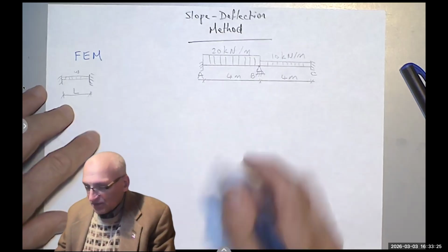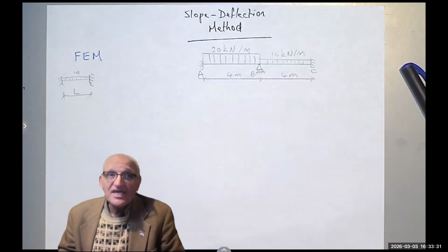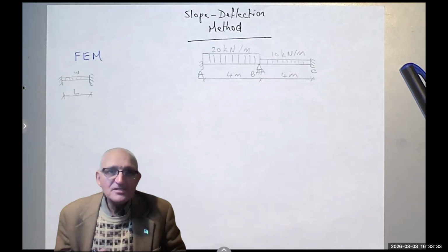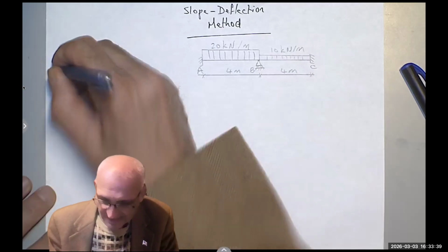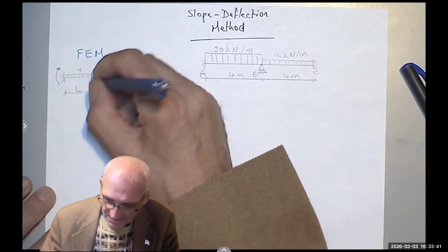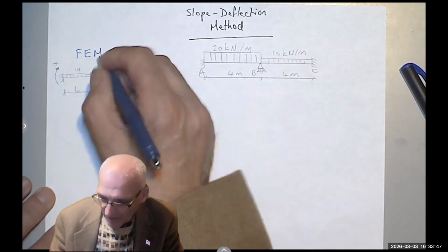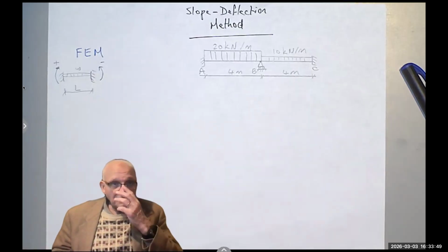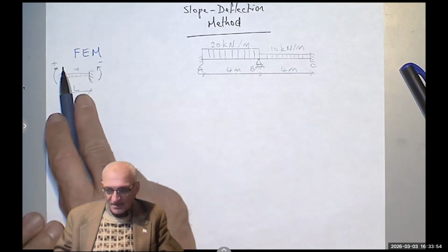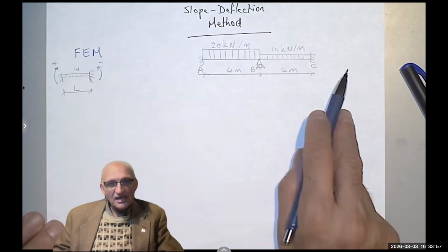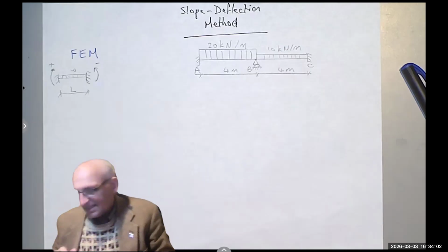Notice that after that, we are going to look inside the beam to find the reactions at the supports, in which case I'm going to switch the sign of the moments. Because if I get a negative moment, meaning it's going clockwise like that, and this one will be counterclockwise, so that would be positive because it's going clockwise, and that's negative. Okay? But then if I end up with a clockwise moment here, it would be negative when we analyze the beam, and this would be positive, right? So you have to be careful with that.